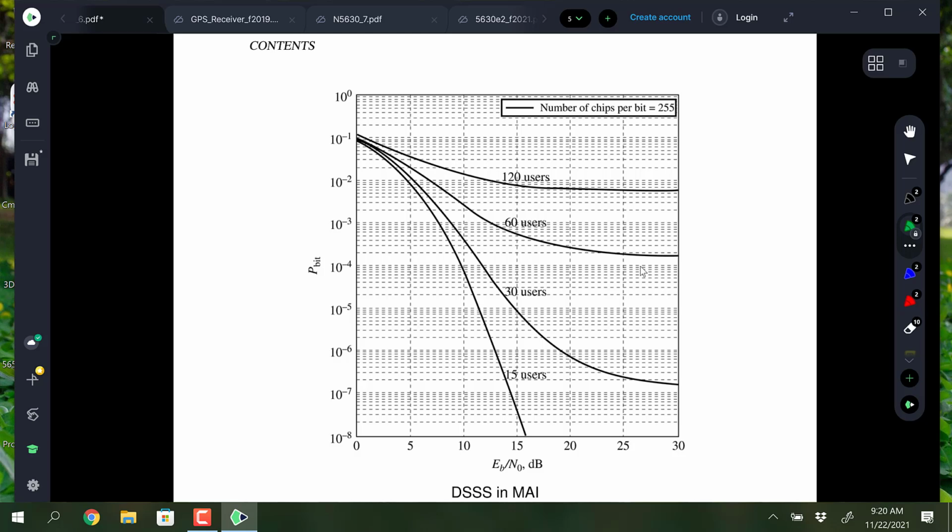Now we have arrays that can be on base stations, and if we look up behind the campus, we can see examples of that with some of the newer cell sites that are up on the tower, or the new antennas that are on the towers up there. But I mean, the same base station might correlate its same data against like dozens of users or hundreds of users. That's right. And as long as the codes are, like the Gold codes, nearly orthogonal, then everyone else becomes noise, basically. Yeah, but still the noise stacks up.